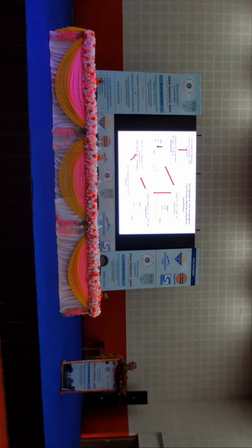If I want a quality product, I should cure it uniformly, correct? If you have differential curing, the quality of the product will be differential. For that reason, industrially it is practiced that you always cure the resin part in isothermal mode.